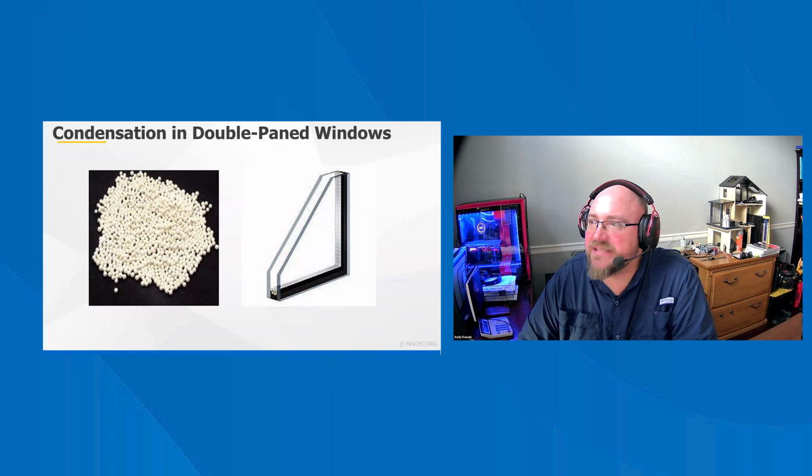A common type of desiccant is silica gel, a porous plastic used to prevent spoilage in various food products, as well as supplied in the pockets of new clothing, within new shoes and leather goods to prevent the accumulation of moisture during temperature extremes that are typical when such goods are shipped from their manufacturers to their distributors in distant locations. In a window, a tightly packed assortment of silica pellets is contained inside the aluminum perimeter strip to dehumidify incoming household air that is not stopped by the window seal.